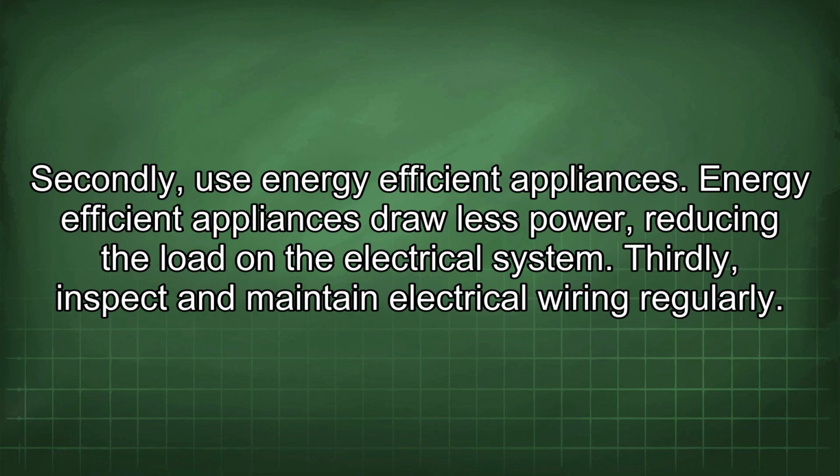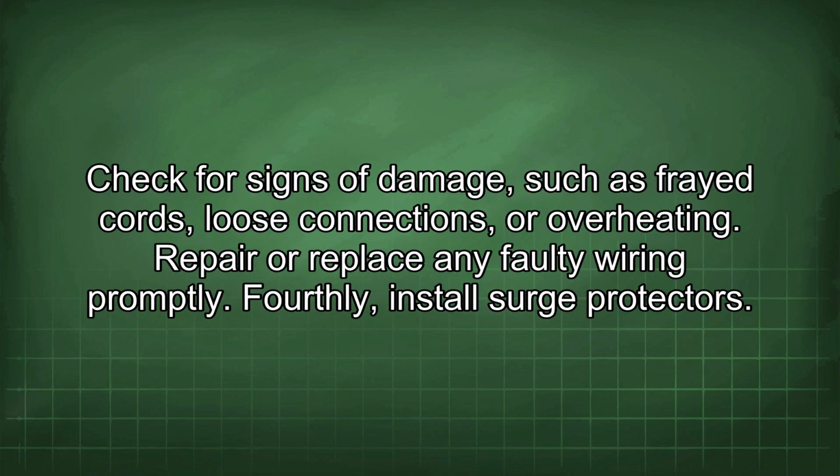Secondly, use energy-efficient appliances. Energy-efficient appliances draw less power, reducing the load on the electrical system. Thirdly, inspect and maintain electrical wiring regularly. Check for signs of damage such as frayed cords, loose connections, or overheating. Repair or replace any faulty wiring promptly.